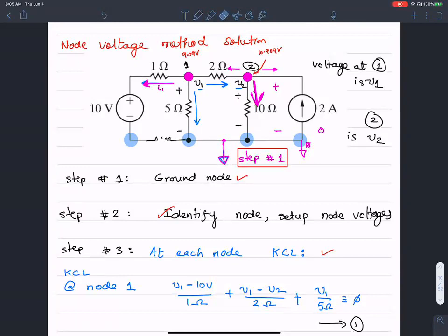If you think about it, the bottoms of all of these terminals are as if they're all bunched together into one connection. So even though it appears like there are one, two, three, four nodes, it's all one connection, and all of the elements are emanating from that single node. Naturally, I pick that as a reference or ground node. Oh, I see. So that's up to the user to decide which one. Yes, I can use any other node as a reference node as well if I so choose.